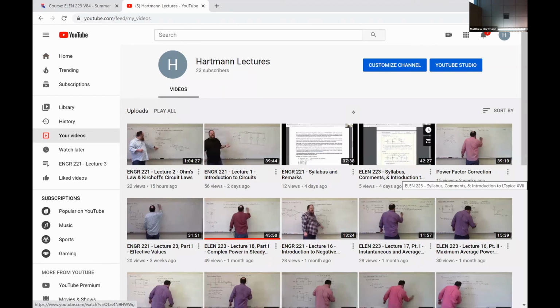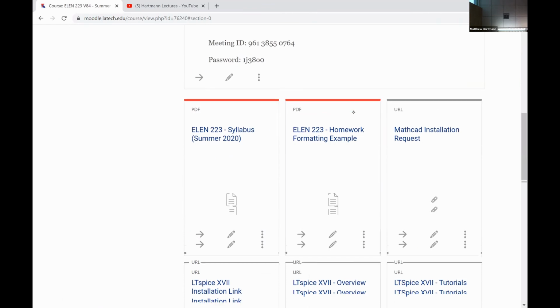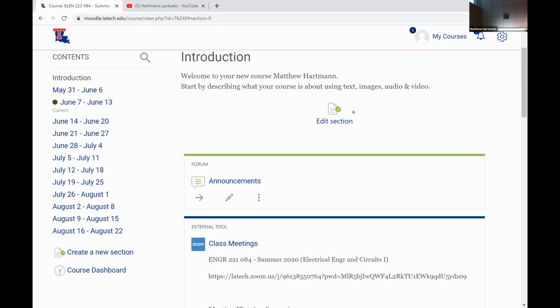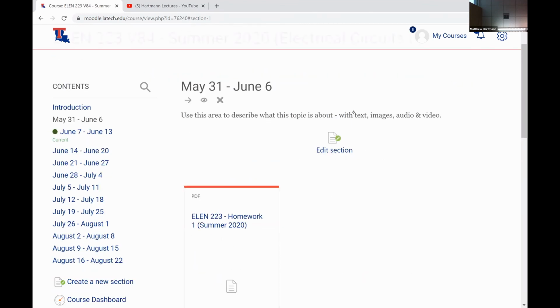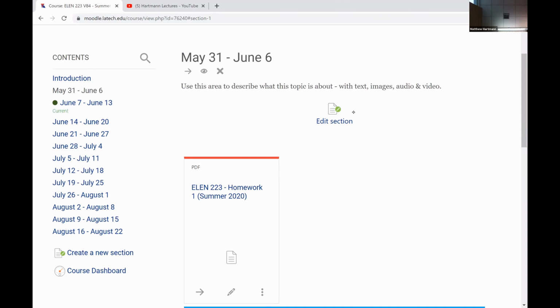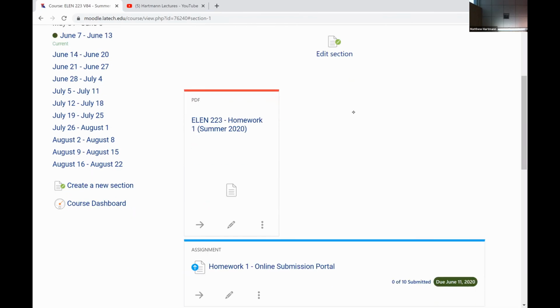So this video, ELEN 223 syllabus comments and introduction, I actually set up a simple transient analysis problem in that. I don't know why I don't have a link to that on this page, so I will put that up. I will put it in this May 31st to June 6th section, which will be class meeting 1, because that was what class meeting 1 was about. So you don't have to go through and find it all. I'll throw a link up where it should be. It'll go through the steps of doing a DC operating point analysis as well as a transient analysis, so that you can see how to set up the initial conditions, and also how you can input a mathematical equation and check it versus the simulation to make sure that your analytical solution is correct. So I apologize for not having that up where it was supposed to go.